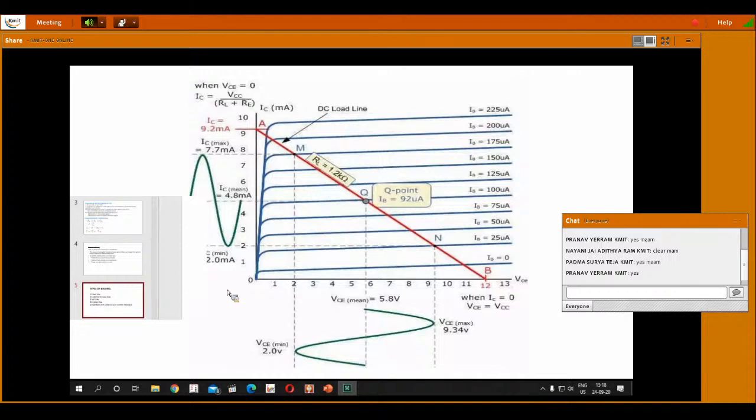So now we are taking the predefined DC values on the transistor by applying the proper biasing voltages on the input and output junctions, with the proper components placed at the input and at the output. So the values of RB, RC, as well as VCE, collector current, the amount of input current IB, as well as the input voltages are chosen based on this selection of the operating point.